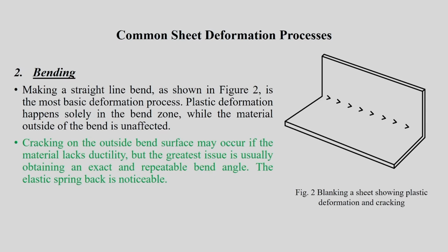Okay. So this schematic is actually a straight line bend. That means this portion was initially horizontal in nature, and we will see in the next slide, there are presses which are used to bend it to about 90 degrees, you can imagine. So the angle is about 90 degrees here, and the bending is done in one line. That's why it's called straight line bend.